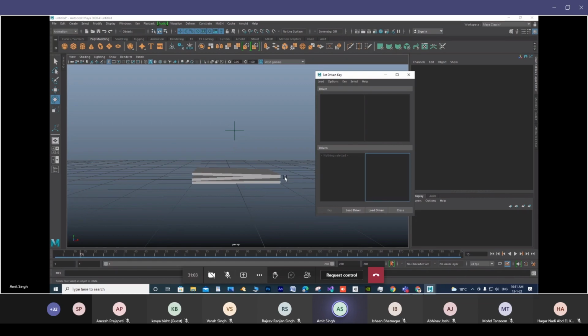You can even, let's say, take one object's transform movement and connect the movement channel to another character's scale, meaning if it moves, it becomes bigger. For example, if this object moves from A position to B position, by the time it reaches B position, the second object scales up, increasing its size by this much. So you have to connect those channels.